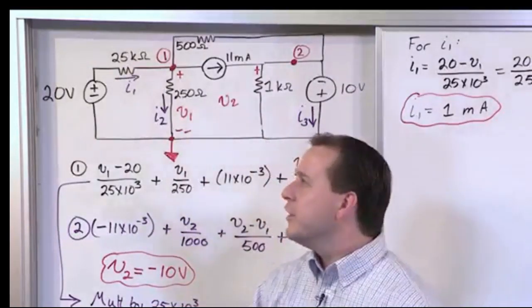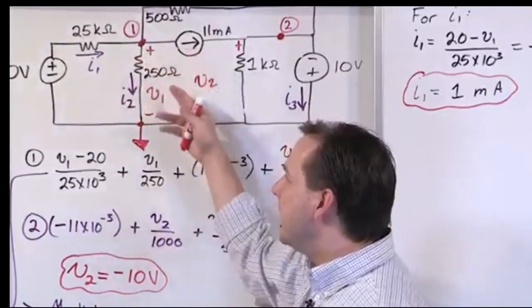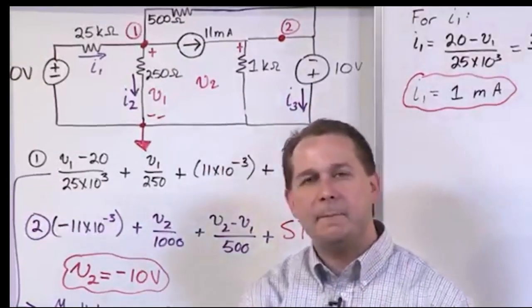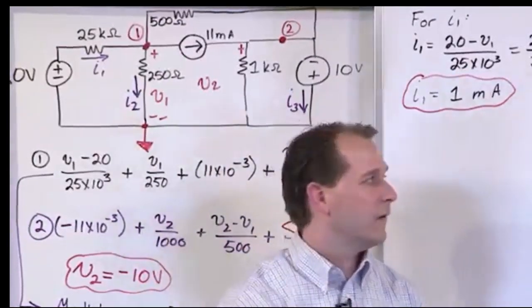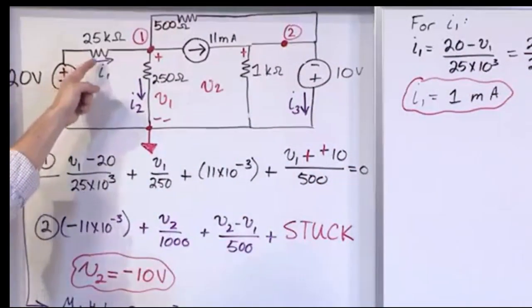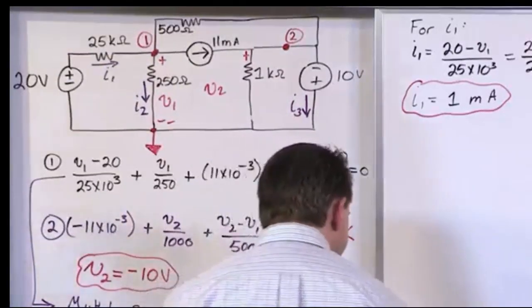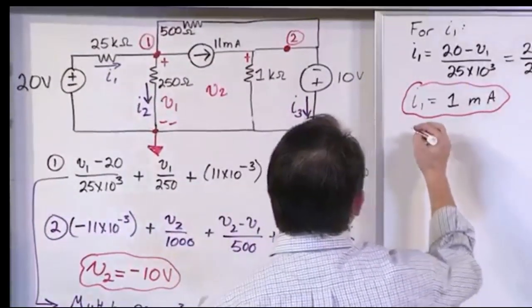No, no, no. You look at this voltage, you subtract this voltage, that gives you the current in this direction. V1 happens to be negative. Let the math take care of the answer. Turns out our current is a positive number, so that means our current really is flowing this direction. And there you go. So let's go and find it for I sub 2.